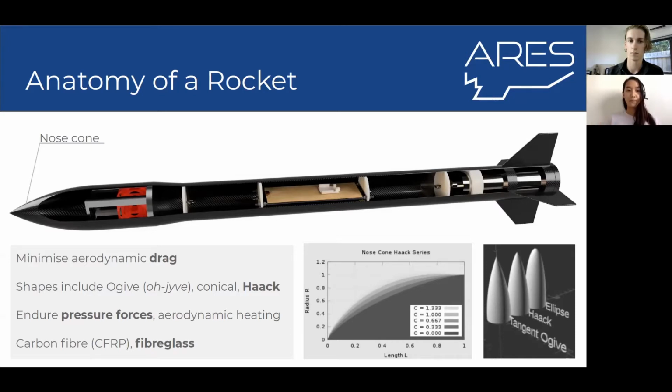But for a higher powered rocket that might experience supersonic flows, so at much higher velocities where the flow is higher than the speed of sound, you would want a more pointed nose cone. The reason is that at supersonic speed you're dealing with flow shock, which you might learn in fluid dynamics, or later on when you've reached there. Essentially, pointed nose cones help reduce the drag at those high velocities.